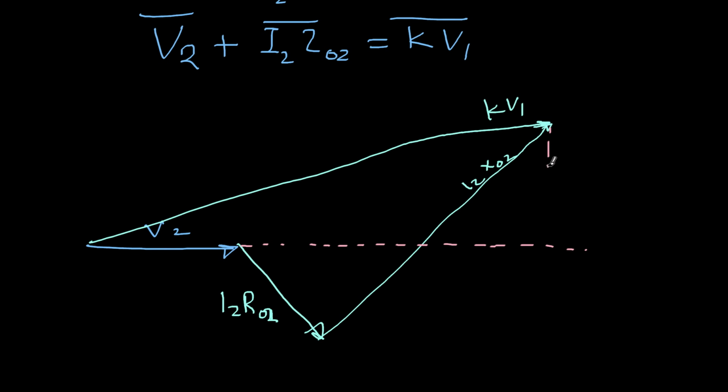So now if I draw the horizontal line here, and then draw a vertical line here, and then if I just draw a circle taking this O and A as radius, let's say it intersects here at B. So the actual voltage drop, let's say this, call it OC, is the terminal voltage of the secondary.